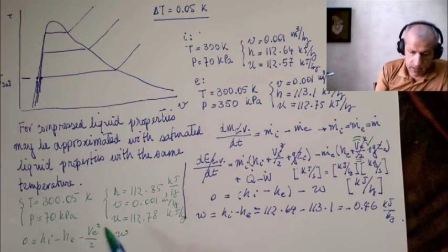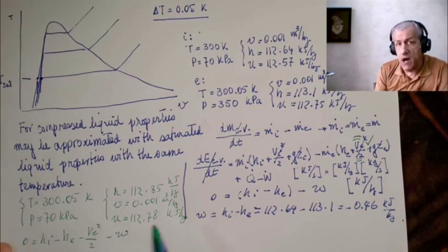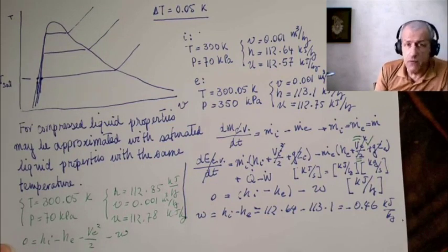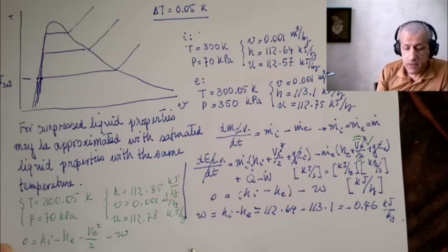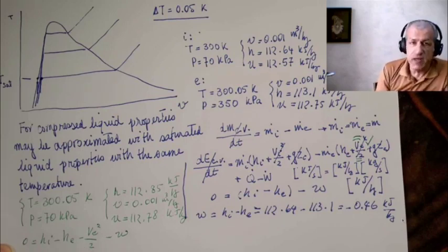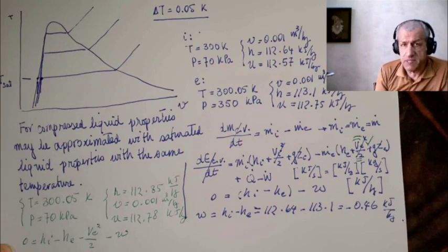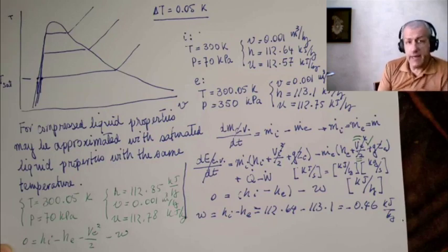Now, just replace values. We have done the same work, but the work is not spent on increasing pressure. The work is spent on adding to the velocity, giving some velocity to the exit flow. This is like what you find in some boats. Speedboats use strong pumps just to give velocity to the water, and they use that reaction to go faster.